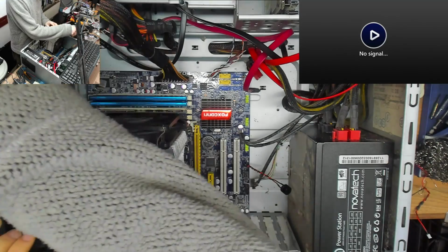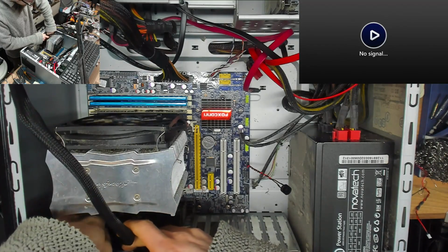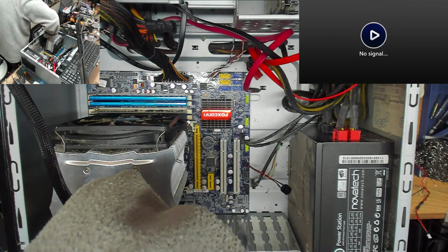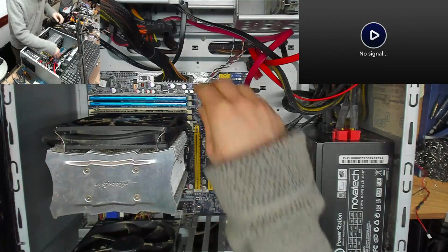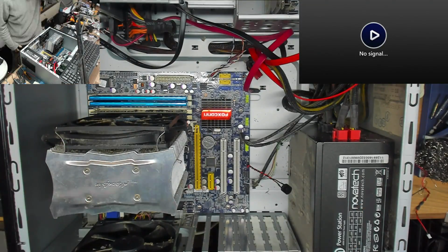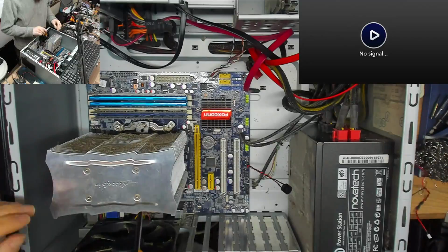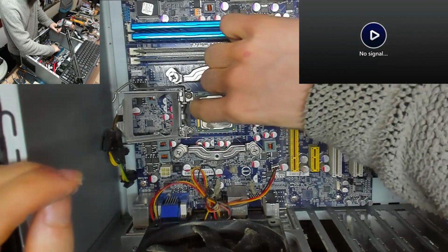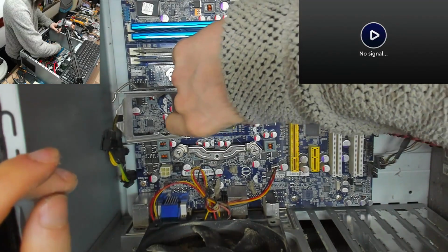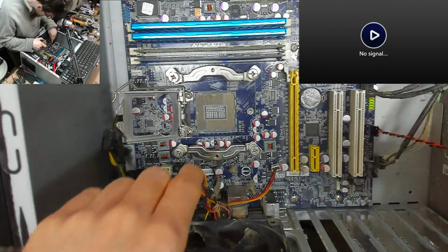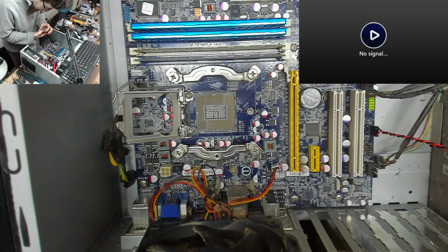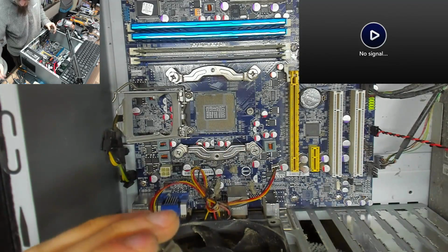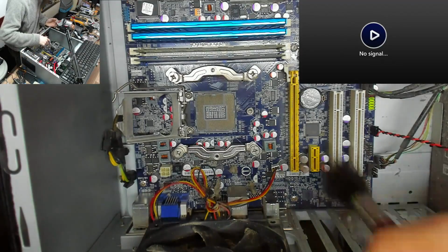Power off at the back. I'm going to unplug the Antec because it's not helping. It's clearly not our problem, so we'll take that out of the equation again. I'm not expecting to see anything wrong under the CPU because it works sometimes. Well, that much being said, there's some dust there. Okay. I'm going to grab the brush and just brush that out.